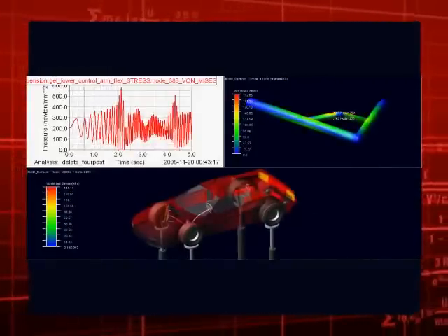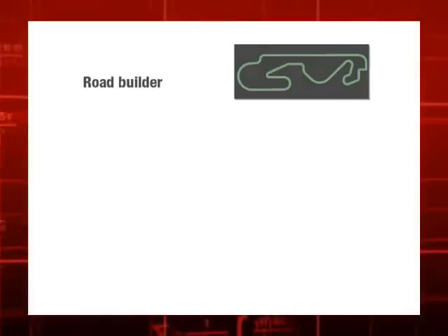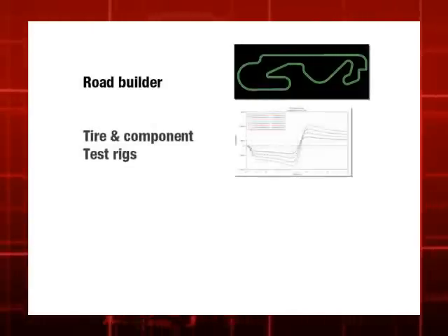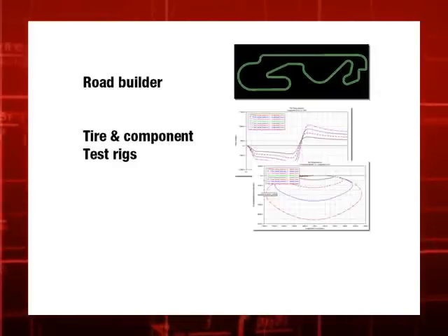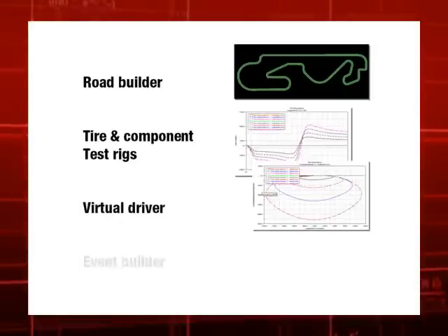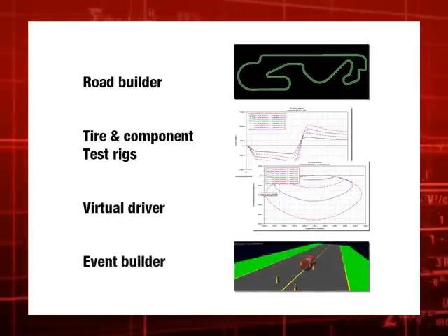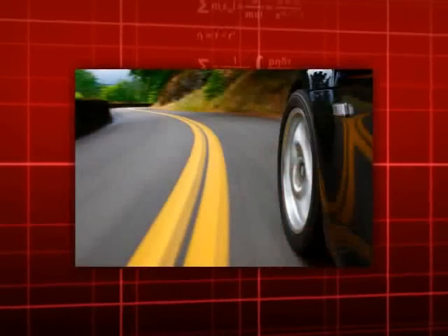This was just a quick overview of a general automotive suspension design cycle. Adams car provides additional utilities like a road builder and tire and component test rigs to facilitate test data input. It also provides a virtual driver interface and an event builder to create custom events, just like testing procedure specs provided to test drivers on vehicle proving grounds.